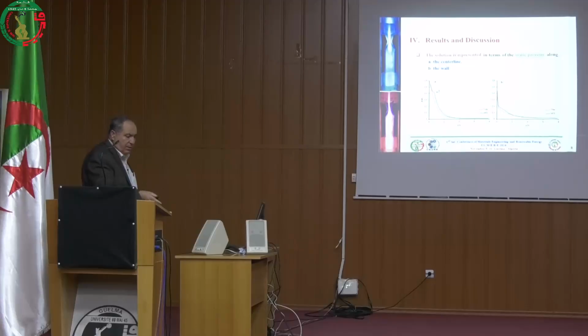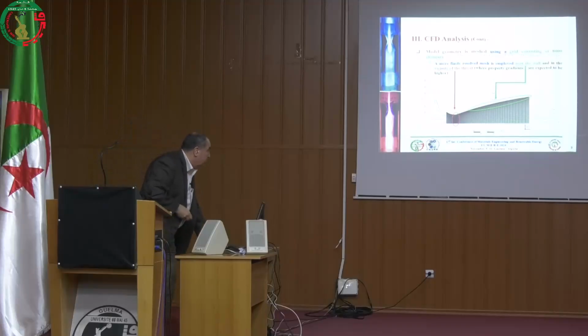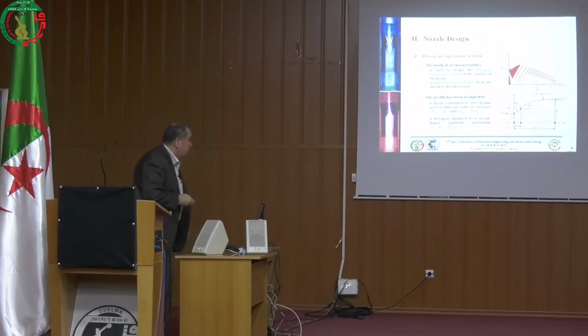The finite volume method is the one applied by Fluent. What we see here is a point of discontinuity that can be sensed by the method of characteristics, but the other method cannot see it. This point A comes from a discontinuity that we know exists. Point A is the attachment point that attaches the throat to the supersonic section. We know that there is a discontinuity here.